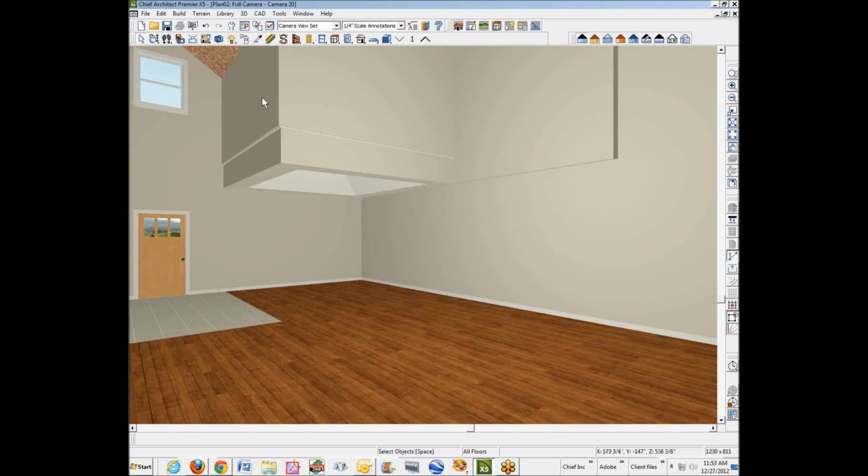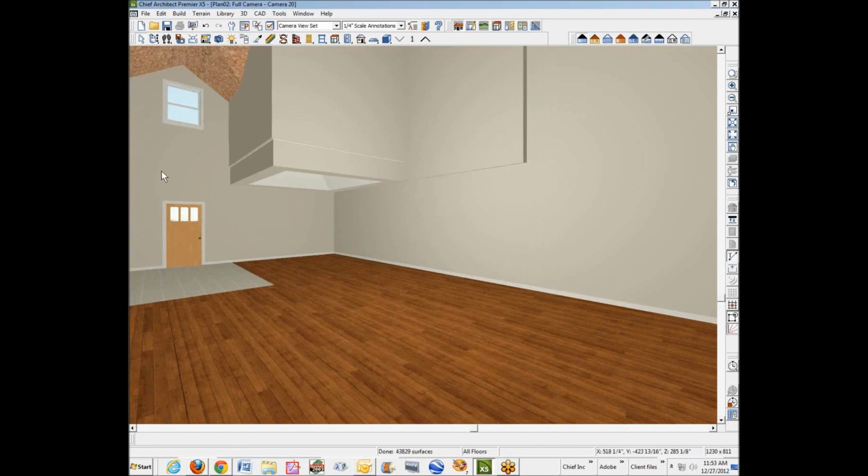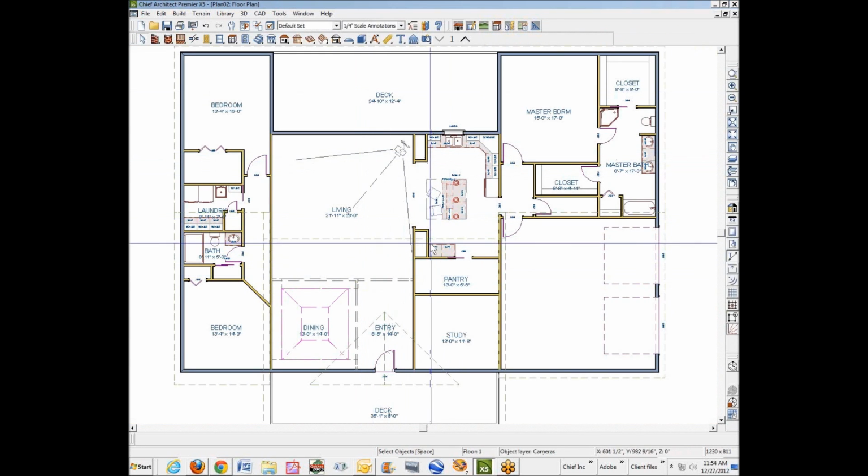That's the delete surface tool, and it just temporarily removes 3D surfaces out of the view. That's kind of what I would expect it to look like. Looks like this wall's not aligned with my invisible walls. That's another story. And to align them up, I'd probably make these walls temporarily visible and then align them. Yeah, I'll just do that.